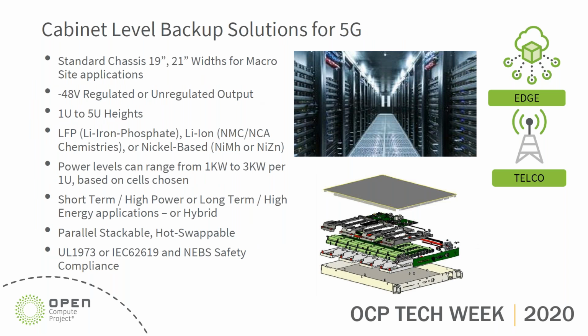The other thing that we're seeing, especially in the telco space, is a larger battery backup type of solution. And this is where this product starts to phase over to the rack and power type of discussions, where if we look at a telecom rack versus a datacom rack, frankly, from a battery backup perspective, the only real difference was the voltage. The telco has traditionally been 48 volt, and the datacom has been more 12 volt. But they're even starting to convert over to 48 volt as well.